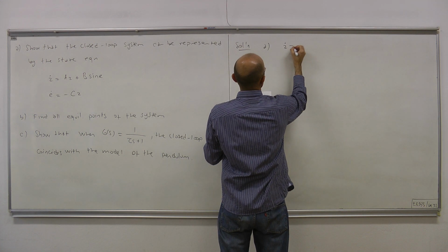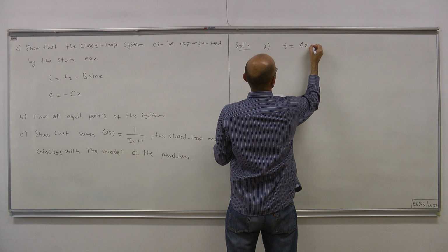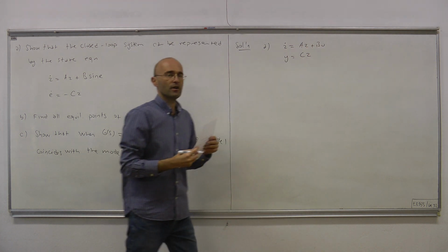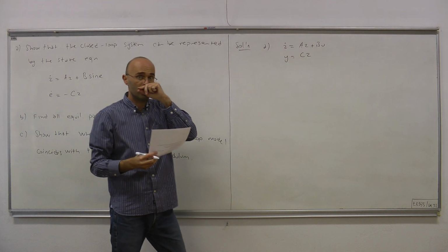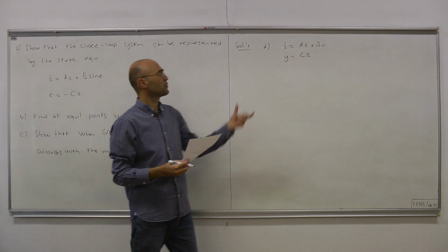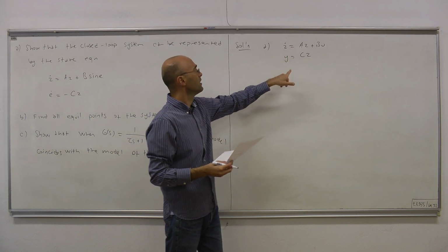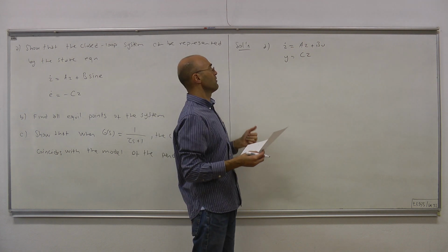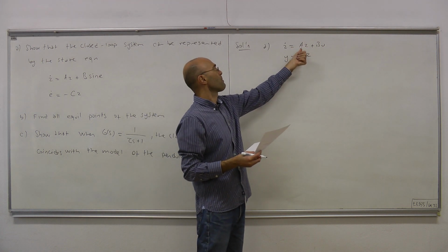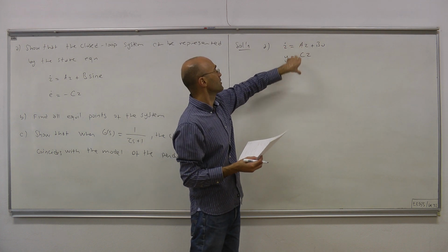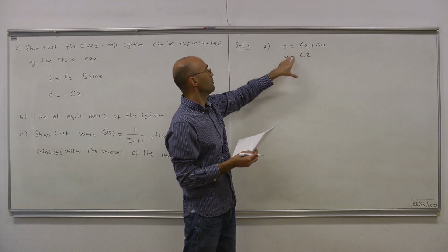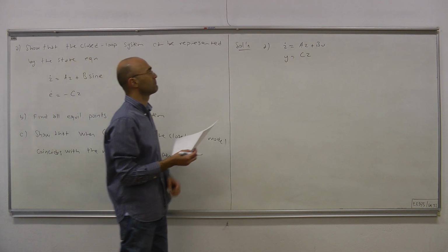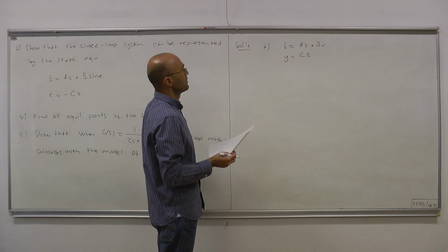So z dot equals Az plus Bu, y equals Cz. Okay, so this is the state space representation of the transfer function G(s). Okay, the output is y, and since G(s), that transfer function, has a realization (A, B, C), the relation between input and output can be put in this form, where z is the state of the system.